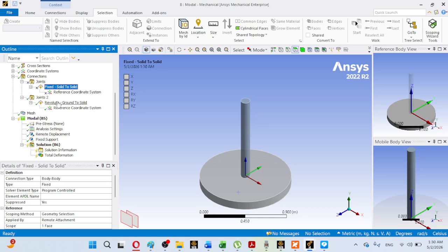and this revolute joint has been applied on this rigid disc, remember, not on this shaft, because this rigid disc will actually be oscillating in the viscous fluid. This shaft is elastic and has no role here. The viscous fluid will be acting on this rigid disc, on this mass of moment of inertia J0. So this is the important thing.